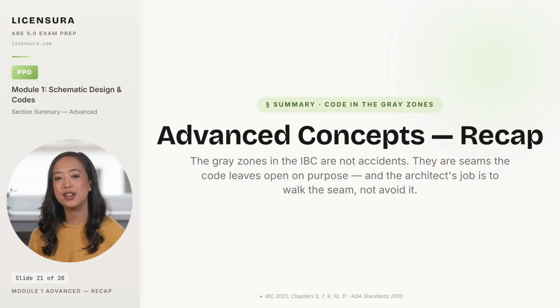Sprinkler standards are a seam. NFPA 13, 13R, and 13D are all correct for some building and wrong for the others. Areas of refuge are a seam that opens when sprinklers close. Zoning sits as an outside seam that constrains the IBC envelope, and Section 104.11 is the seam that becomes a tool when the prescriptive code refuses to fit.